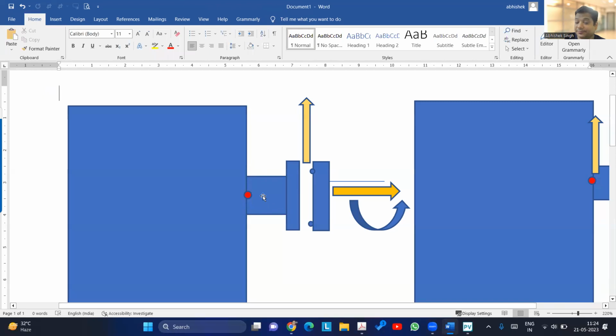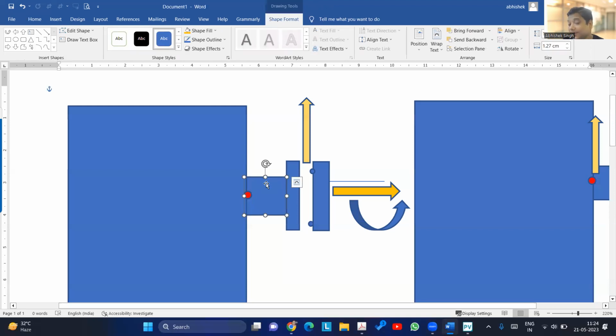Great. So the third is checking the nozzle neck. How will we check the nozzle neck? We create the moments caused by the maximum load. Once I have the moment, I use sigma_b = M/Z, the bending moment divided by the section modulus. It will create two different values, compressive and tensile, so check both.